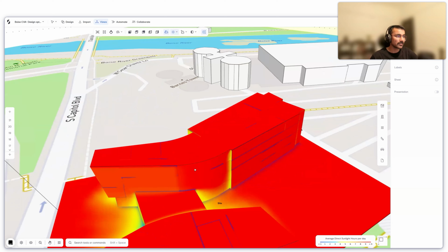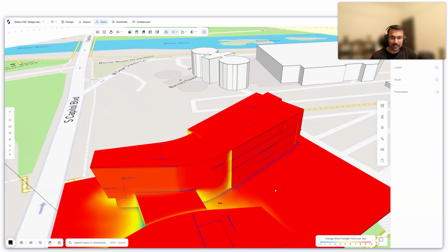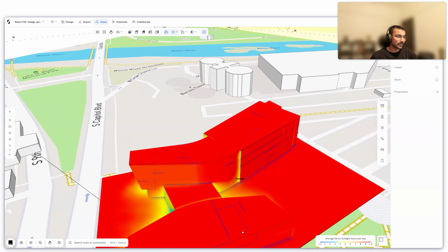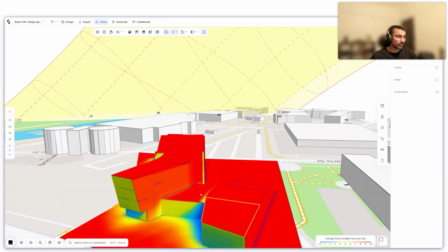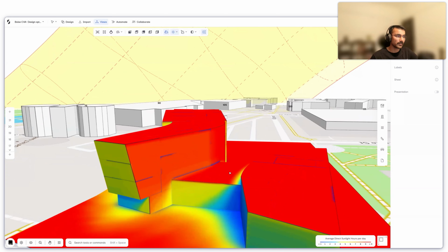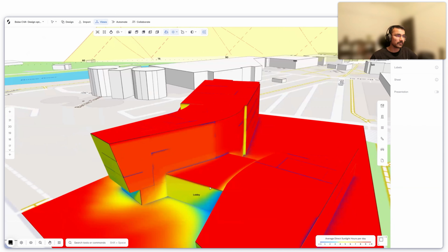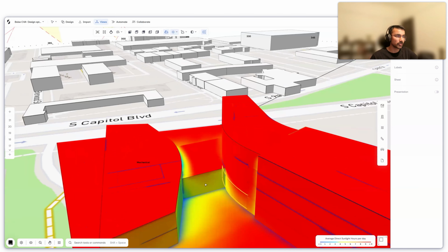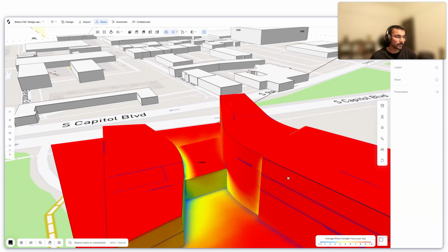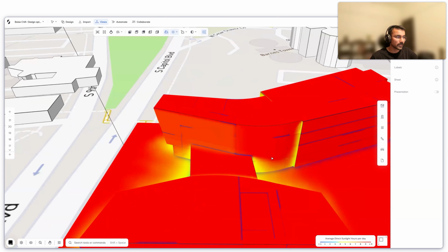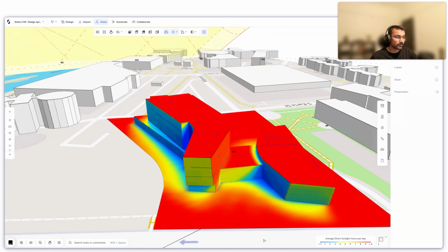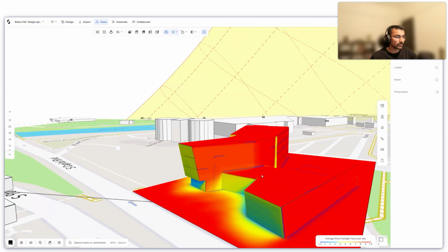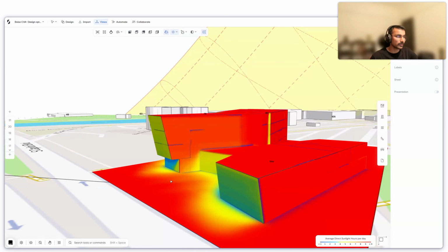It also makes sense to curve this edge here because that will reduce the heat gain in the building. And if we want this lobby space in the middle to be transparent, we do have both the shorter sides available for more glazing. On the western faces, it would probably make sense to have these overhangs extend out a bit.